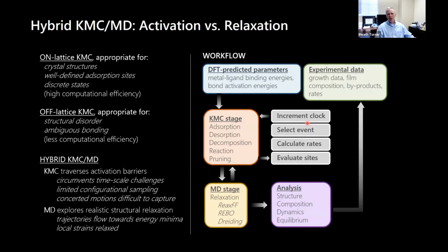And so this is really the heart of our method: we're performing a hybrid kinetic Monte Carlo and molecular dynamic simulation. And this is really what it looks like if you look at the workflow on this right-hand side. So what we do is we have different events that will happen in kinetic Monte Carlo. So these are reaction events where these precursor molecules will come down to the surface, they'll decompose, they'll form bonds with their neighbors, and this film will grow. In the desorption, the side products will desorb from the surface.